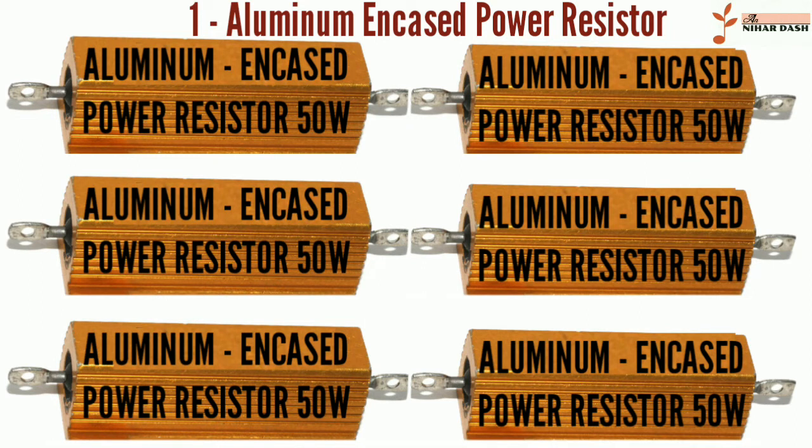As the name suggests, these high-power resistors are wire-wound resistors encapsulated in an anodized aluminum housing, which itself acts like a heat sink. The aluminum casing may be further bolted onto an external heat sink to maximize heat conduction. A wide range of resistance values can be supported using this type of resistor. The goal is to ensure maximum winding uniformity, rapid heat transfer, reliability, and stability for the connected device. This type of construction is used for the highest power levels.